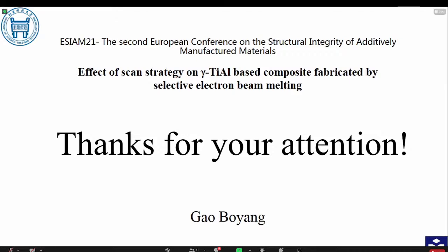Looking as we have a little bit of time for questions here, and I don't see one yet, but I have a couple actually. So you need to process your materials at quite high temperatures, right? Some 800, 900 degrees C. So how about the reusability of the powder afterwards? I mean, that's for the raw material in powder form, quite demanding temperature already. So do you have an idea how completely you can recycle the unused powder? Is it still usable for a second build job?